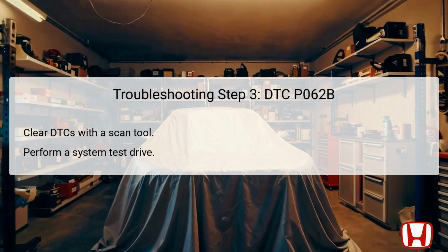For the third troubleshooting step, the objective is to clear any diagnostic trouble codes stored in the PCM using a scan tool. After performing necessary repairs or adjustments, using the scan tool to clear DTCs is essential to reset the system's memory. Following this, a system test drive should be conducted to ensure that the PCM is functioning as intended and that the MIL does not illuminate again.